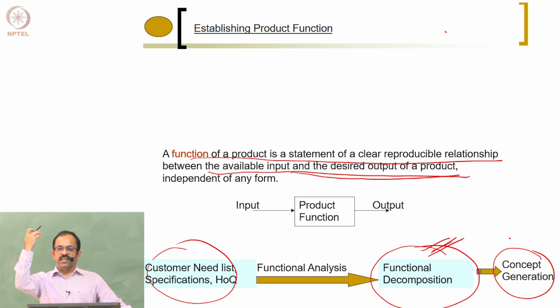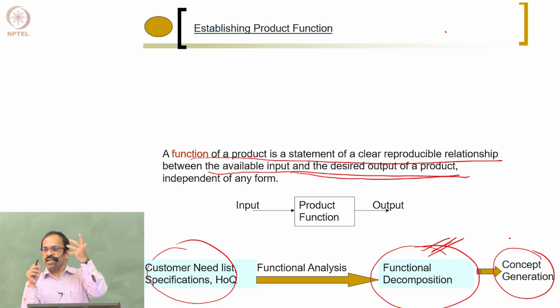For example, you have a fan here. The fan has a particular function and structure. Now, I want to redesign and make a new fan. So I need to know how the fan is actually providing air circulation. I look at each and every function inside the product and see, can I modify the way the blades are attached to it, or can I change the way the blades are positioned, oriented in a particular way? If I change it in a different way, I can get a better product. That is basically how I develop a new concept to develop a new product.